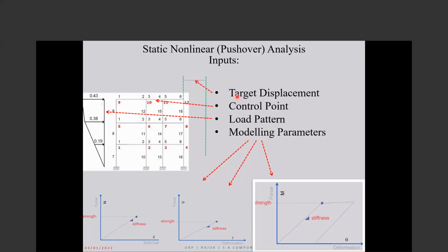So it's numerical. We try changing the software; usually the software tries to do its best and reaches the targets. But sometimes it's not a numerical problem. You ask for this building, the demand in this level of earthquake is, for example, 50 centimeters, but the capacity of the building is 5 centimeters. So whatever you push it, it doesn't go more than 5 centimeters. That's one possible result. So then what happens? We say the building will collapse in that earthquake.